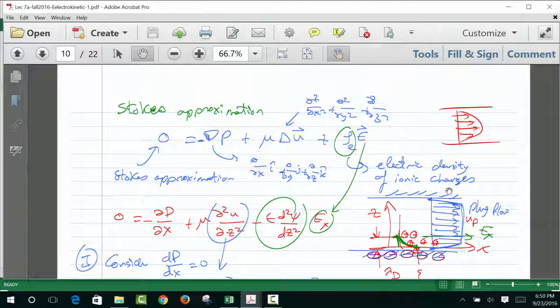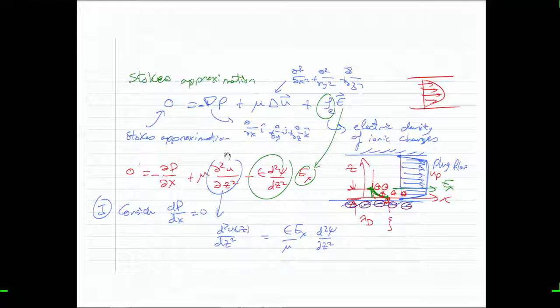Back to our mother of all equations. As far as we are concerned right now, the mother of all equations is the Navier-Stokes equation. So this is the Navier-Stokes equation, yes, but of course I canceled a bunch of terms on this side. What did I cancel? This is in the x direction, so this is the u momentum equation. I canceled partial u, partial t, because it's steady state. Yes, they are moving, but it's the same flow rate all the time.